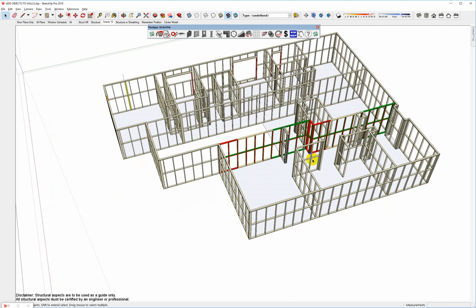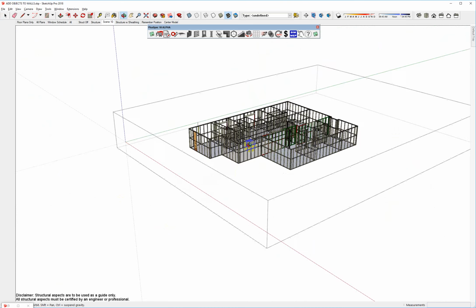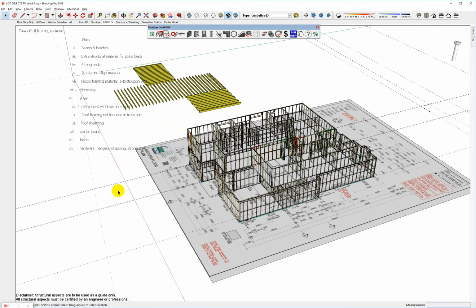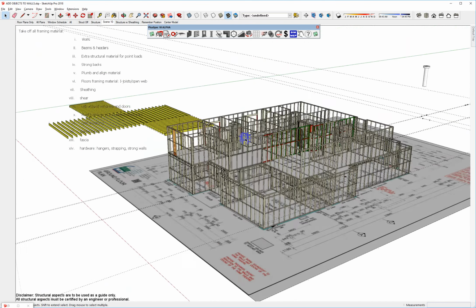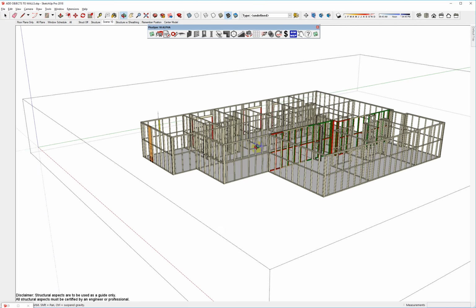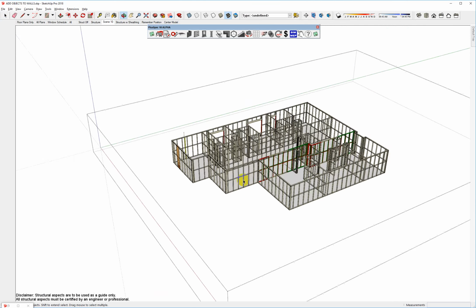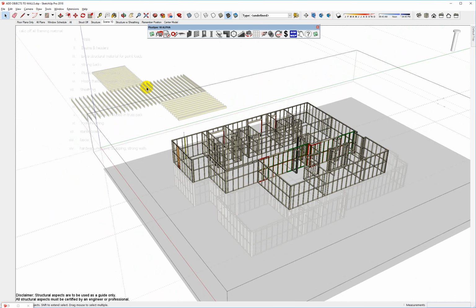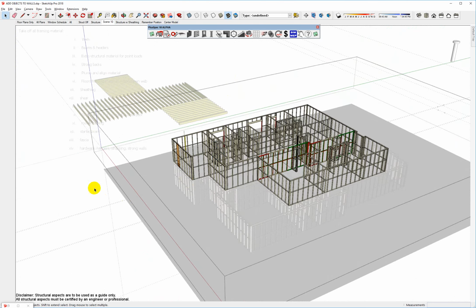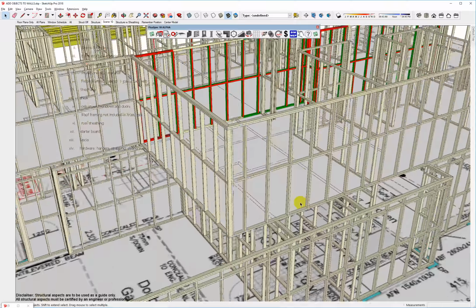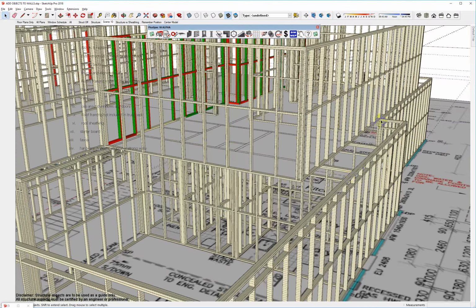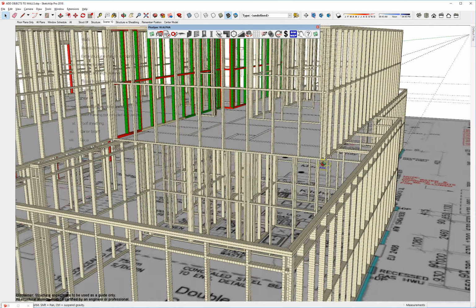around there. So, okay, and you'll also notice that I don't actually have my bottom walls turned on, because when I actually broke inside of my component, I have a thing called hide, rest, and model, and we can train you on that as we go. And I can turn it off. So Control Hide is my shortcut for it, and now I can see that my top walls are overlapping my bottom walls. In this particular instance here, the ground floor walls and the first floor walls don't actually line up, and that's just the design of this particular project.